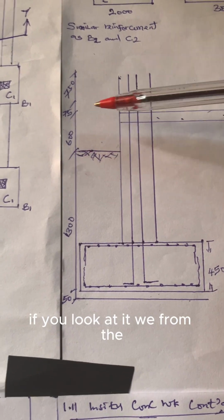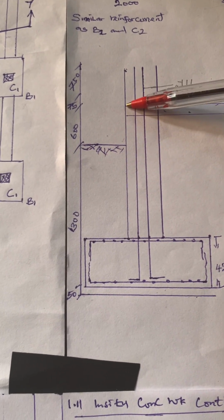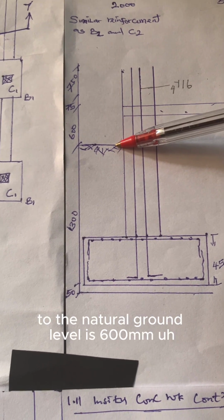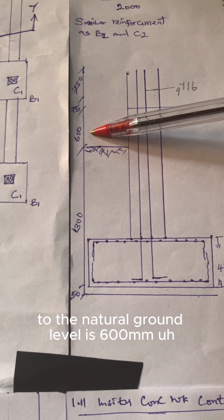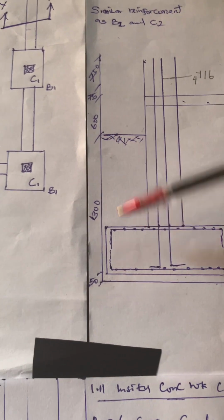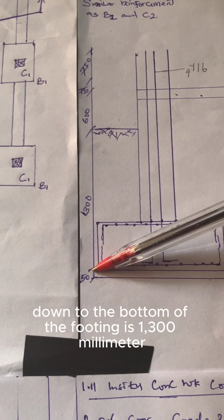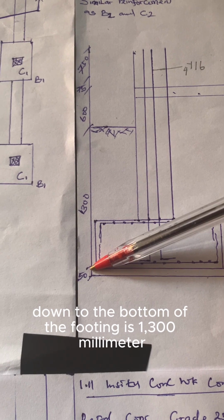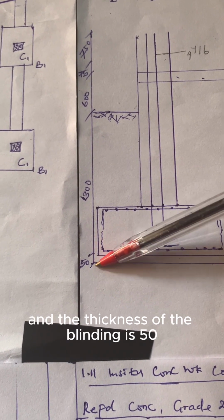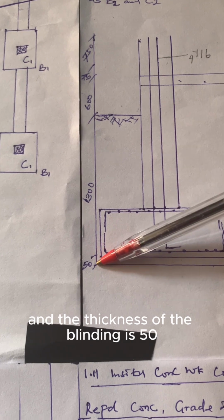So the actual height of the column starter, judging from what we have at this point: from the concrete bed to the natural ground level is 600 millimeter, and from the natural ground level down to the bottom of the footing is 1300 millimeter, and the thickness of the blinding is 50.